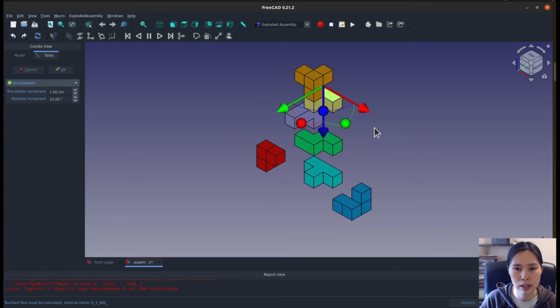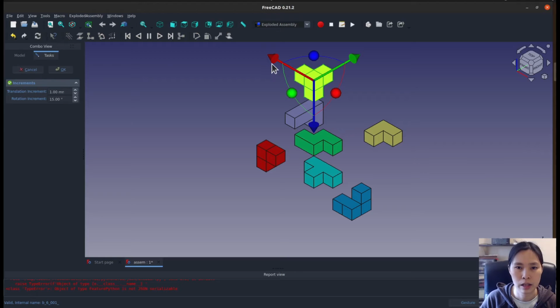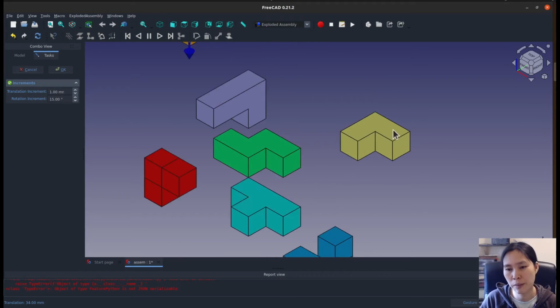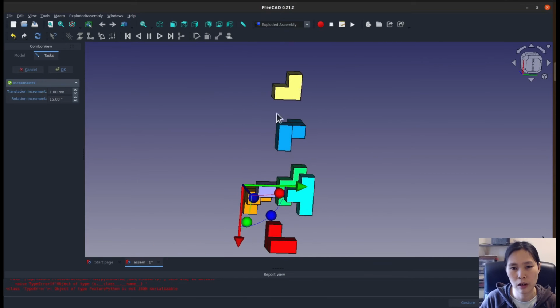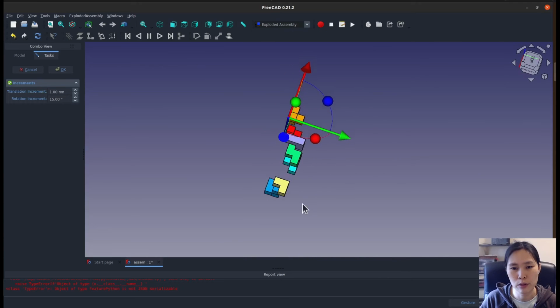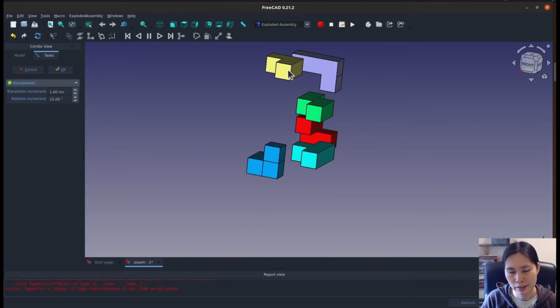If you look at the model that we have over here, it's pretty simple. Let me just move this out so it's easy to see. I say the V is the simplest because, as you see here, it's just 3 cubes that all go together. If you draw a sketch of this shape and then extrude it, meaning you push it to the height of this, then you can easily create this shape.